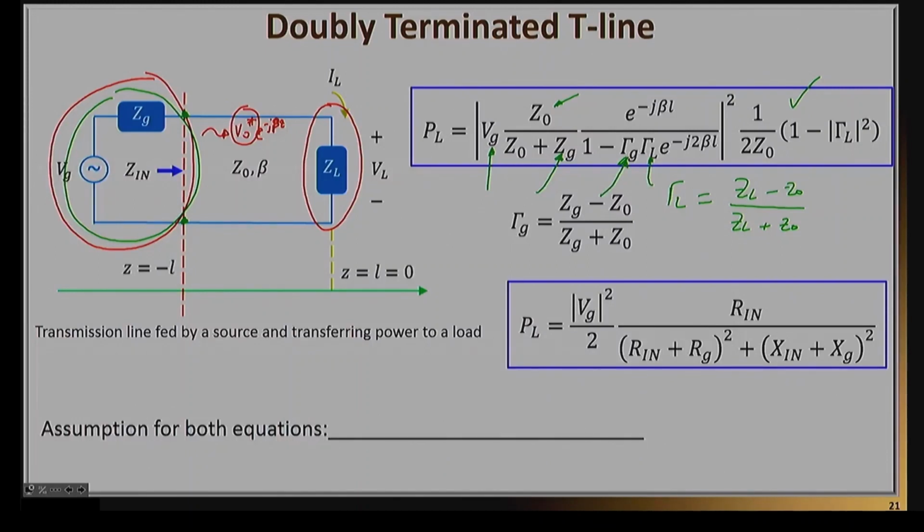That's the reflection coefficient that depends on the difference between the impedance of the source Zg and the impedance of the line Z0. So that equation, again, is very similar to what we had seen before. You might recognize this term here. Essentially, that equation has been calculated by taking the incident wave and subtracting the reflected wave, and then replacing that V0 plus with the excitation knowledge. And so that V0 plus has basically been replaced here.